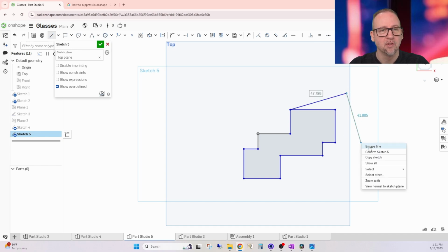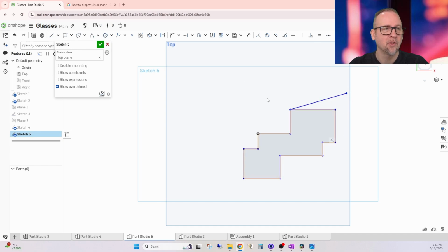So if I want to change it, let's say I was just using lines, and this line, and right click and escape that line, and if I click a line again, and line, let's say L for quick keys if we want. Okay, and if you do a certain shape, it will start to create round. But if you go straight up, it's going to create it like that. So let's say we created this shape right here. We did some trims on this. We're going to trim this, and we're like, oh no, we wanted this horizontal, and this one horizontal, and that one perfectly vertical. So that's when we click on our lines.